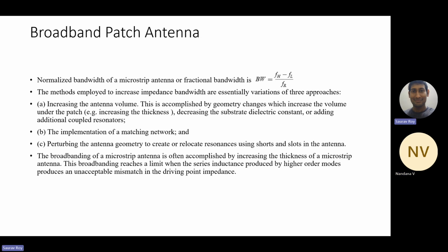So that's why they are saying that there will be a problem in driving point impedance. There will be a mismatch. Understand, right? Because the feeding length increases, now there will be a problem in impedance matching. Your S11 will not be good anymore.